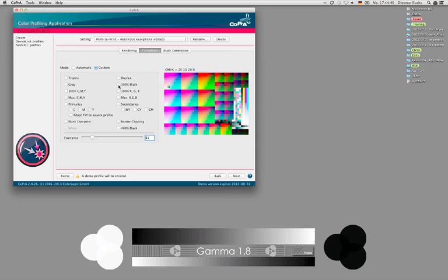So, for example, if I want to make sure that 100% black is not rendered into 4 colors, but stays as 100%, I switch this option on, and here it will show me where this color is in this example image. There are 2 patches which have the same 100% black value. This would make sure that only 100% black is not touched and is just kept as it is.